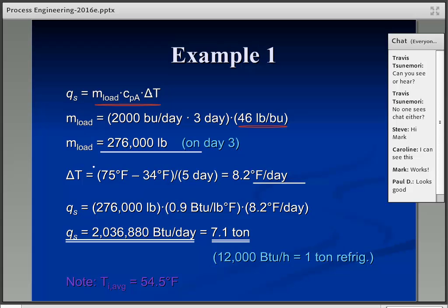And again, there's just a certain amount of understanding the problem statement there. It was specified those apples will be cooling off over a period of like 5 to 10 days. And so all the apples that went in on day 1 are still being cooled at that rate on day 3, along with the ones that went in on day 2 and the ones that just went in on day 3. So you have to use all 3 days of apples to account for the total cooling load.